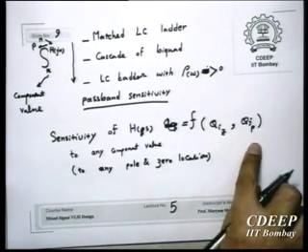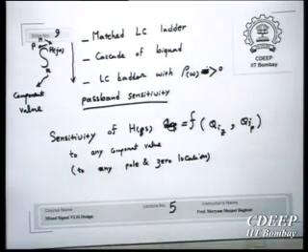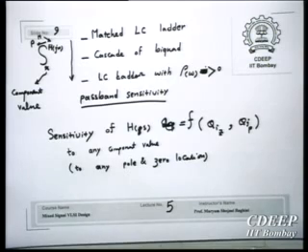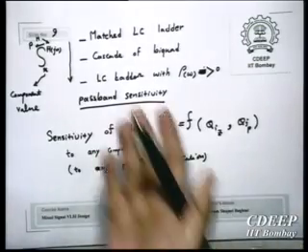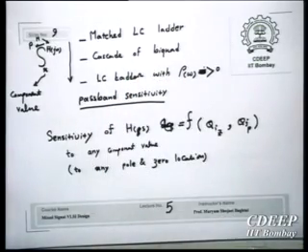So if Q increases, this sensitivity will increase. Therefore, designing sharp filters is always a problem, and it is so whether you go with a cascade or a direct implementation.